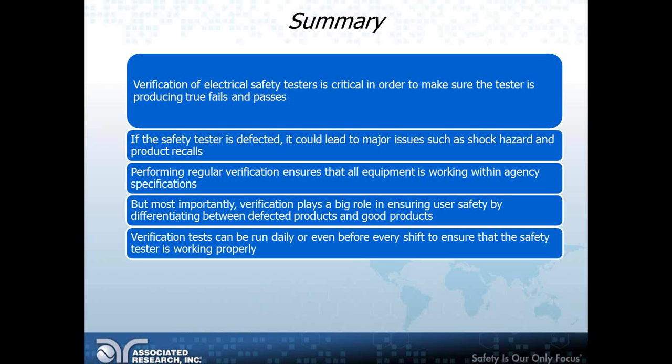Think about a bad product being out in the market and somebody, the end user, getting shocked or injured. That could lead into huge issues with companies being sued. So this stresses the importance of running verification tests on electrical safety testers, because once again, an electrical safety test is only as good as the tester itself. Using a simple resistor in series with the output of an electrical safety test equipment will assist in validating measurements and ensuring that the failure detectors are functioning properly.